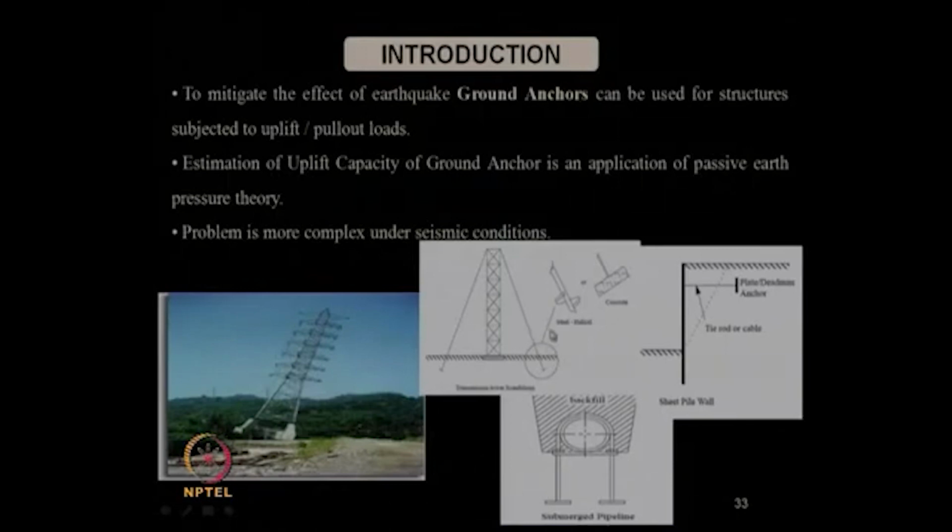These pictures show you can have steel helical anchors or concrete anchors. So, various types of materials can be used as anchor plate. Even submerged pipelines are always put with anchor support at different intervals along the length of the pipeline. Otherwise, when there is an uplift force, the pipeline will come out from the embedment and open up.